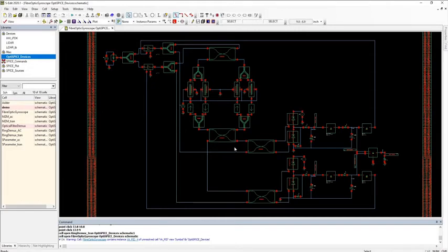So what happens is, as the rotation rate changes, the resonant frequency for the forward and reverse propagating waves changes. So we use the control circuit to make sure that the signal going into this ring resonator tracks the incoming frequency, so the resonant frequency of the ring. So by tracking the resonant frequency changes in the ring, this circuit is able to track the rotation rate.